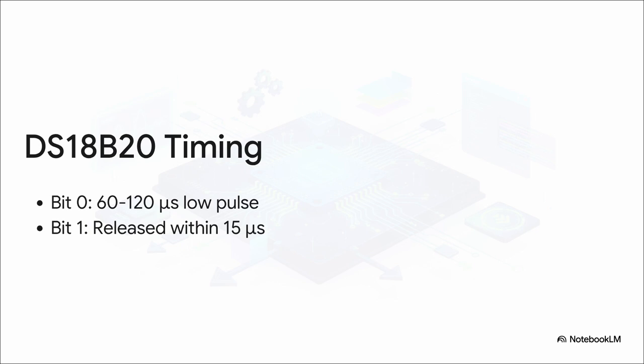A standard one-wire sensor doesn't have a clock line at all. Instead, it requires hyper-specific microsecond timing constraints just to register zeros and ones. To write a bit 0, you have to pull the line low for exactly 60 to 120 microseconds. To write a bit 1, you pull it low for just a tiny fraction of time, and you absolutely must release it within 15 microseconds.